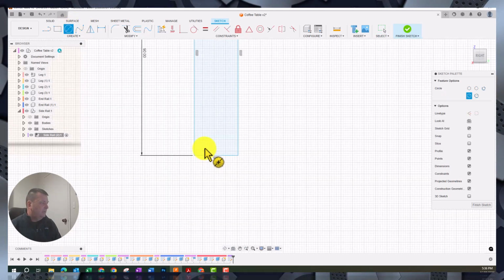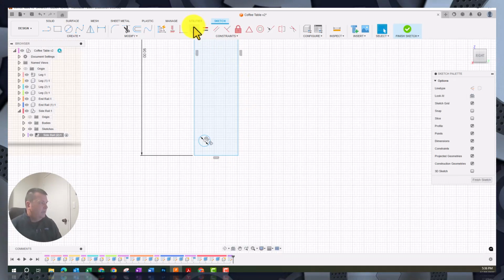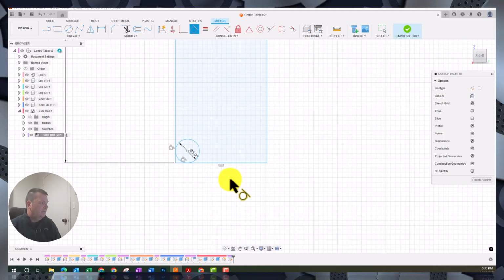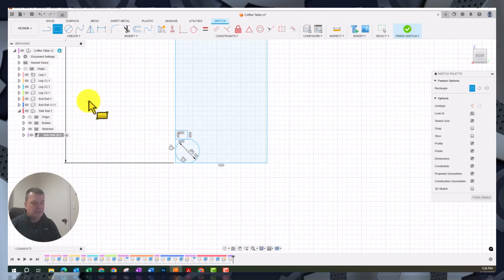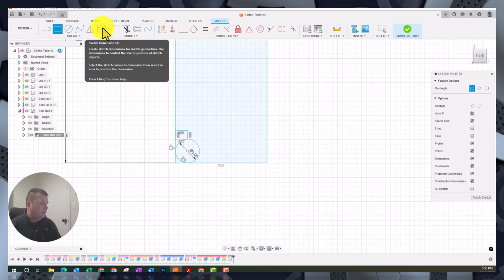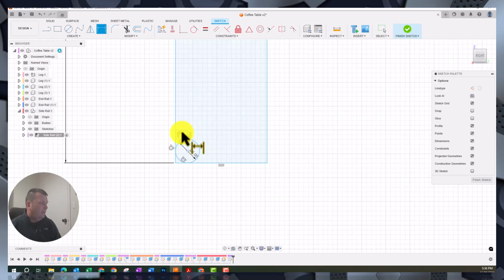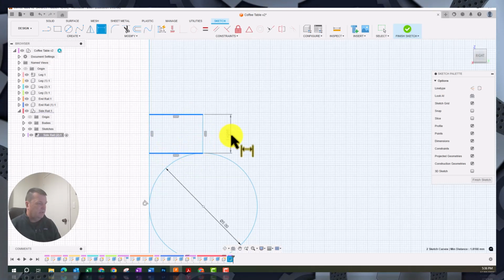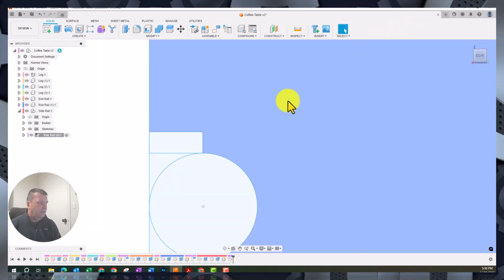While we're in this sketch mode here, we're going to draw a little circle, make that 5, constrain that again to the bottom of the box and to the side of our shape. Get the rectangle tool, draw a rectangle from the edge of that to the edge of that. And I forgot to dimension it, so to fix it up, you go to the sketch dimension tool, which is that there, or you go to create sketch dimension. And so to fix that up, we want the distance between this line to this line, and there's 2 clicks there, is 1 millimeter. Go like that, go finish sketch.